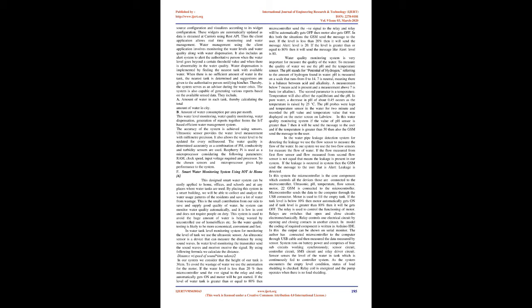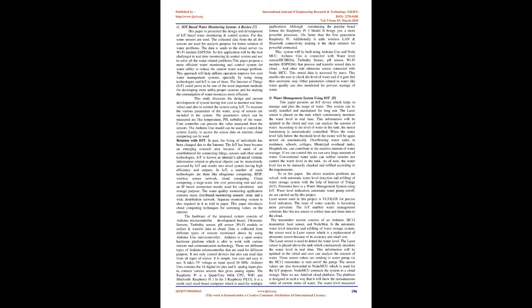The second parameter is temperature. Temperature will also affect the equilibrium and the pH. In pure water, a decrease in pH of about 0.45 occurs as the temperature is raised by 25 degrees Celsius.